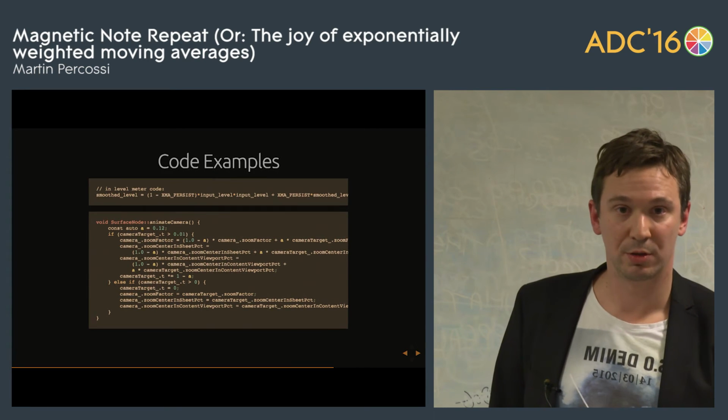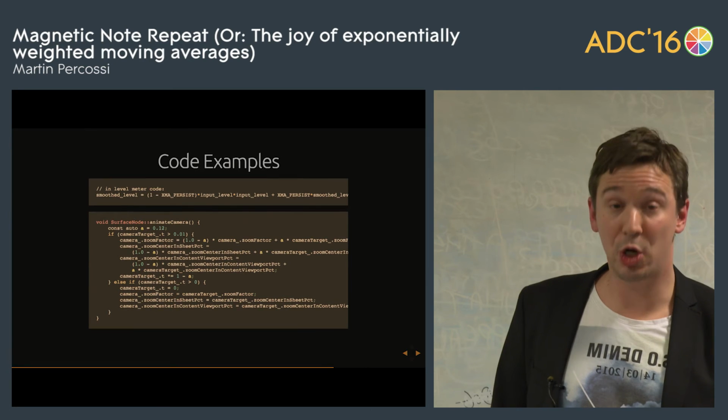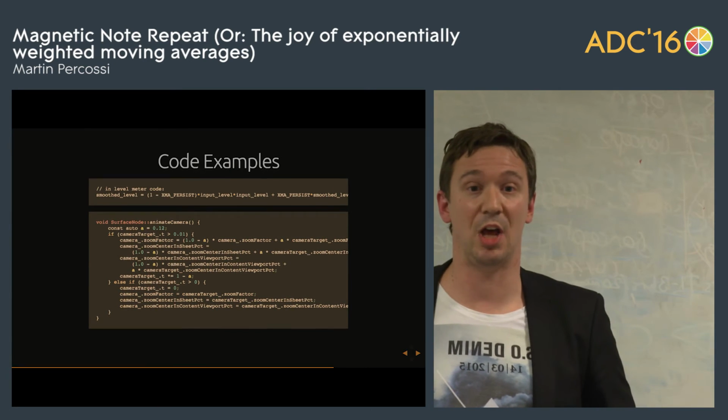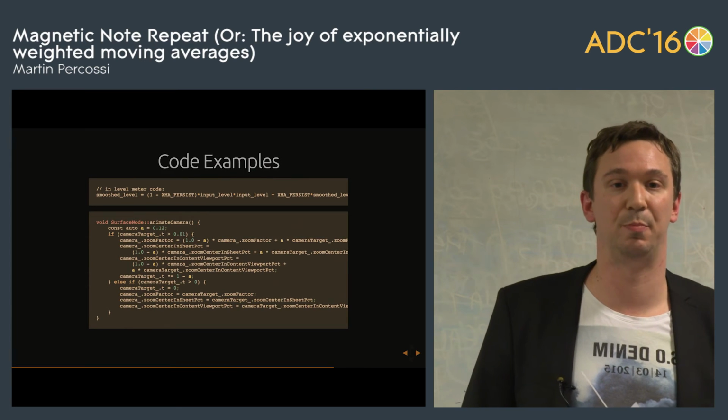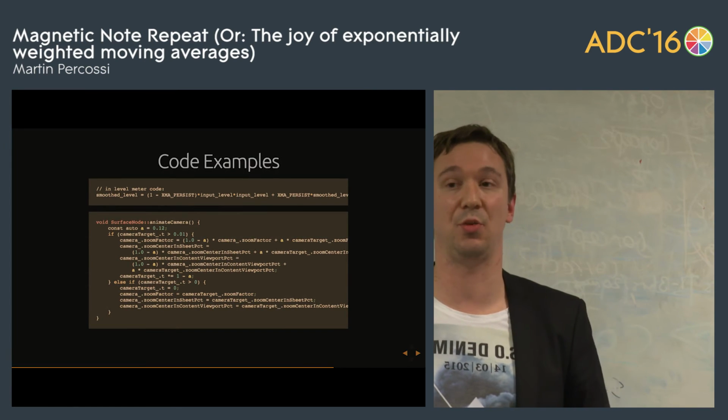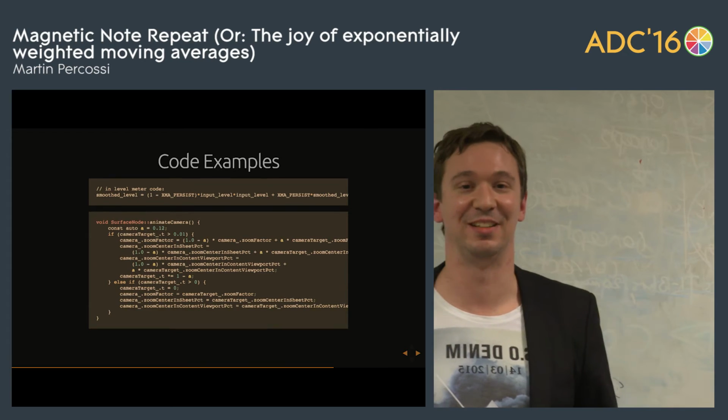Well, why are you squaring the input level, just to avoid the negative? No, because you want the root mean square, right? Otherwise, you can also take the absolute value of it, right? But otherwise you're going to get negative values for that, right?